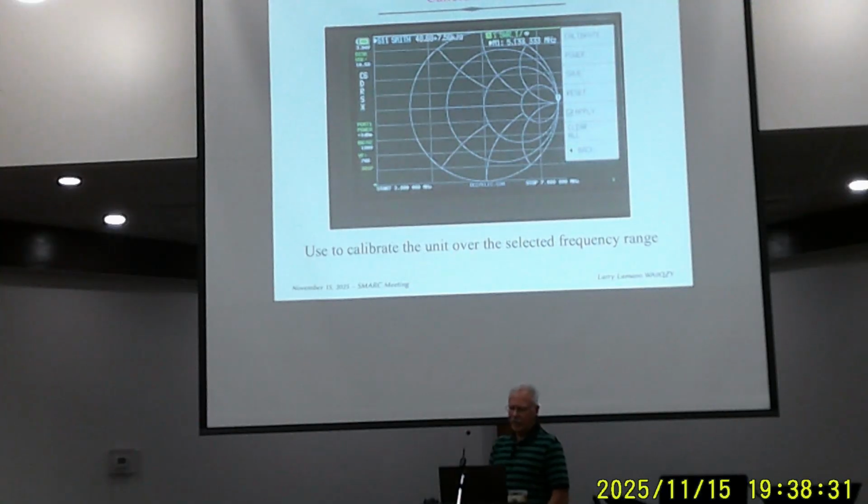The well-known calibrate menu. Okay, so when you go to the calibrate menu, now there's calibrate power. So the power is that +1 dBm over there. So again, that's something you set once and never mess with it. You can save this, but when you go through the calibration, it also has the save screen, so I'm not exactly sure why that's there. Reset will actually reset all the parameters. So say you've already calibrated this to something, but you want to erase that out because you want to recalibrate it, so you do a reset.